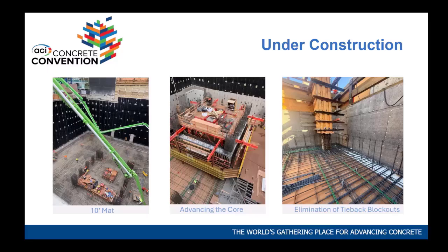You have trucks coming in. So think about it, 10 feet of concrete, it's mass concrete. There's a high heat of hydration, so we always make sure that the cement content of these mixes is less than 450 pounds, and we extend the strengths, so you don't need that strength till about 90 or 120 days, to make it easy on the ready-mix guys to bring those mixes to us. If you pour that mix like a regular 6,000 mix with 600-pound cement, you won't be able to walk on it in 2 days. It's going to be very hot. So that's one. Two is we cover it so we keep the heat differential the same between the center and the top of the mat for a few days till things come down. We'll look at the temperature gauges for that.